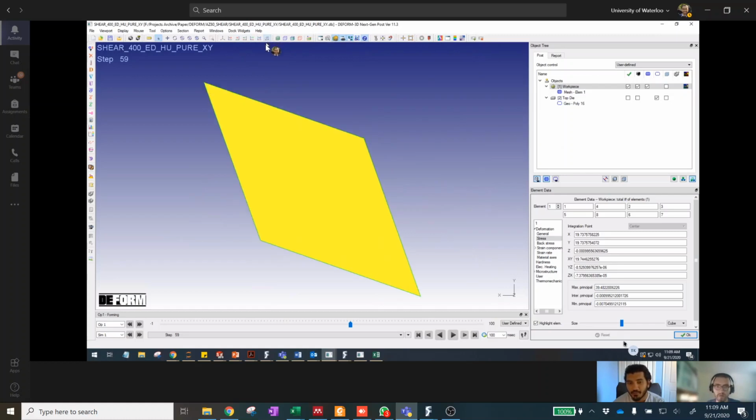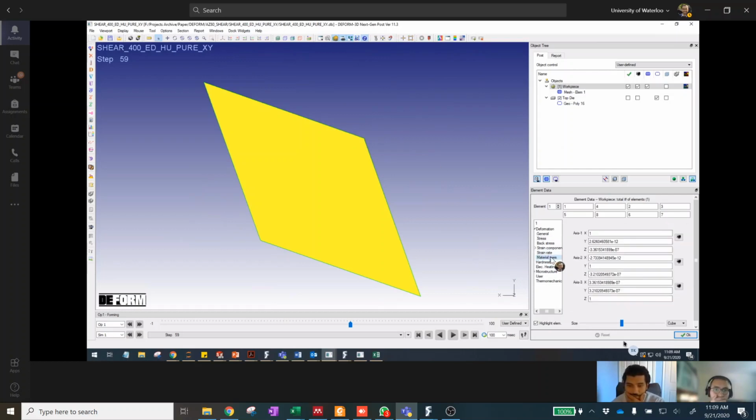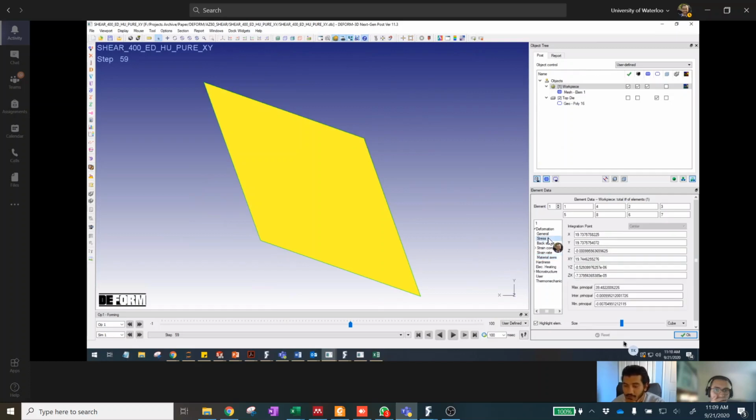The one downside with the element model is I can't visualize the material axis. If you click on material axis, it doesn't show you the vectors pointing in the right coordinate system. So it gets kind of tricky to verify it's correctly oriented.